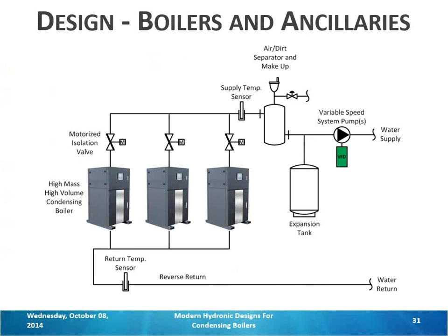And then a sequencing panel that's controlling our boilers, controlling the isolation valves, monitoring supply and return temperatures, controlling the pump, and monitoring differential pressure, while feeding all that information back to the building automation system.